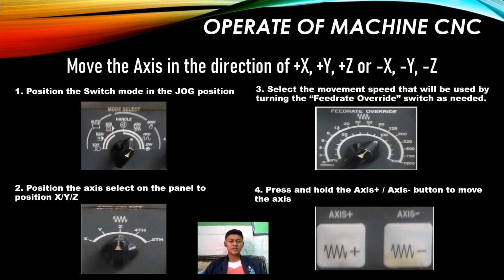Next, move the axis in the direction of X, Y, Z. One, position the switch mode in the jog position. Switch jog.